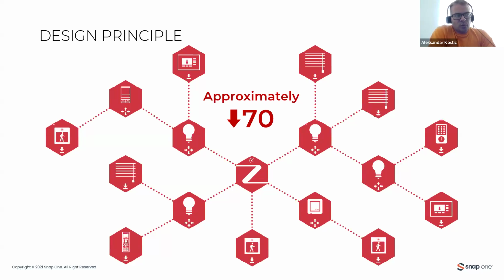So in situations where we have a setup like that simply by our standard Control4 design, we don't have any controller which is an ideal candidate for a Zigbee access point. Maybe everything is in a rack, or in a room where the controller is far from the place where the Zigbee lighting controllers are located. In that case, I would suggest to use a controller just as a Zigbee access point.